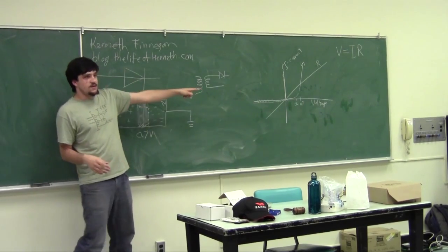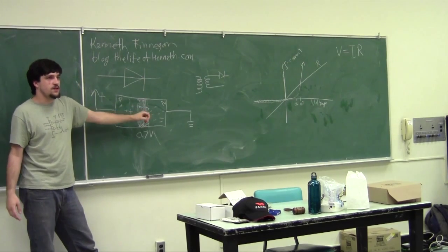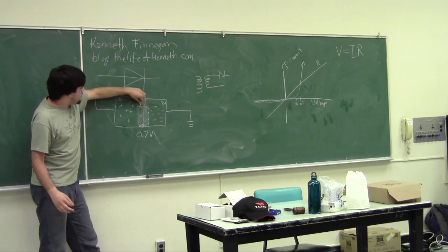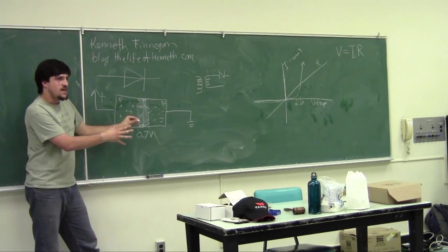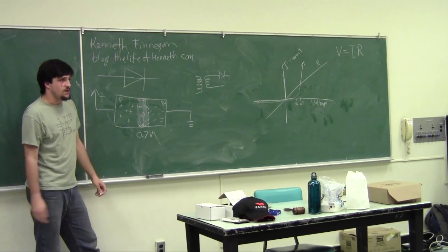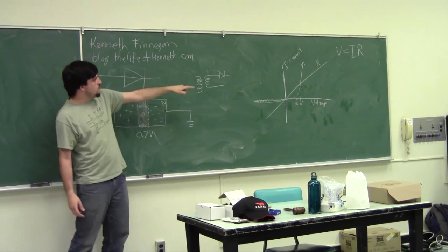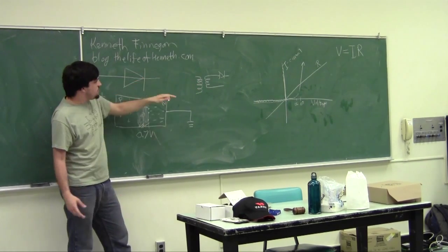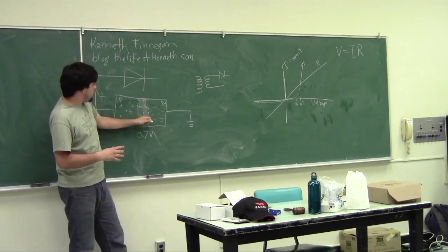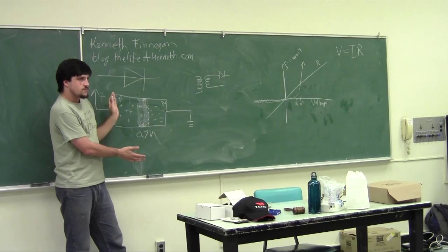Right? Because it's not actually any single value. As you pass more current through it, if you pass just enough current through it to get rid of this depletion region and you have charge moving through and everyone's happy, you're still going to get little pockets of depletion region, which are then going to get canceled out again. That is why, as you apply more voltage, all of these trace bits of the depletion region get wiped out and you get even higher current, right? So that is the diode, right?